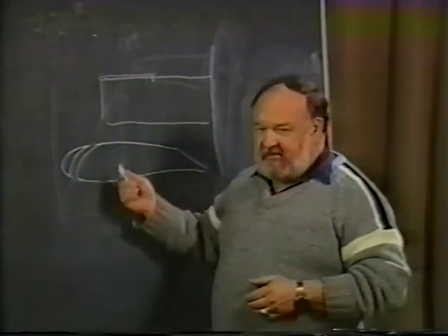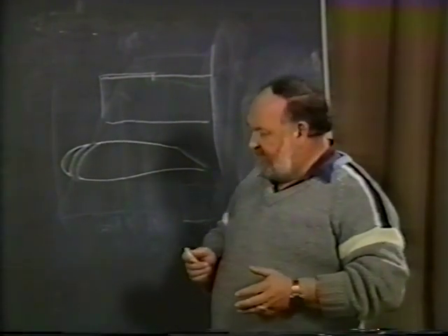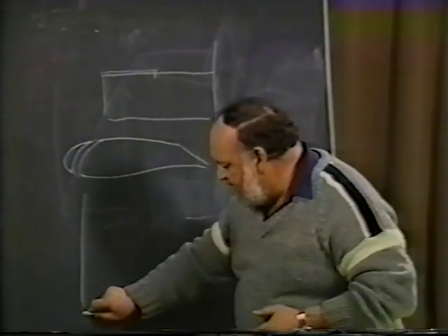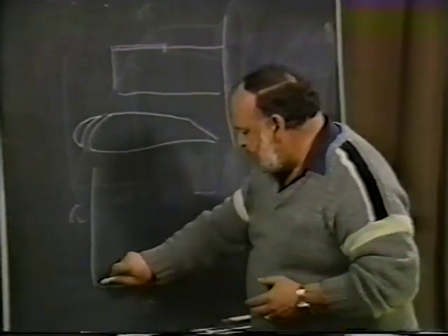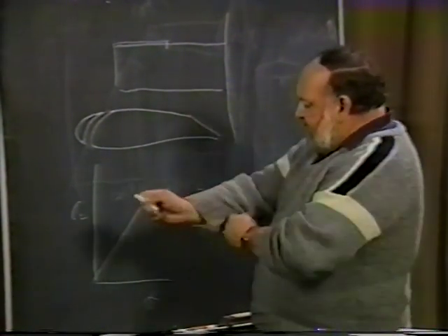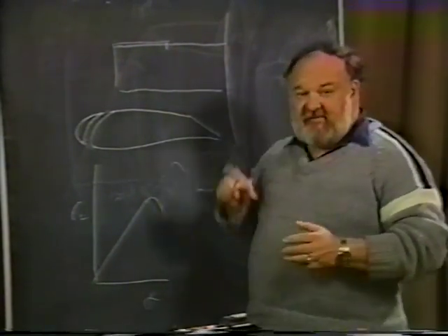But a properly designed slot will give a very definite effect, primarily in the fact that it will take, go back to the old famous lift curve slope, your CL versus alpha. What it really does is take the original curve and just keep extending it on up, sometimes as much as 5, 6, 7 degrees.